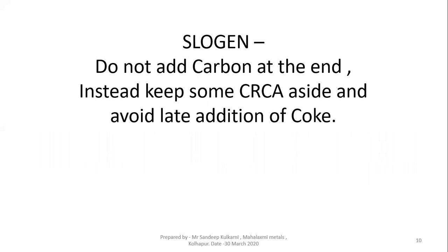Now we go to another slogan, which I am sharing with you again. It has been shared with you a number of times, but again I am sharing it for your ready reference. Do not add carbon at the end. Instead of adding carbon, keep some CRCA or MS scrap aside and avoid late addition of coke. It is very important to avoid late addition of carbon to get better efficiency.